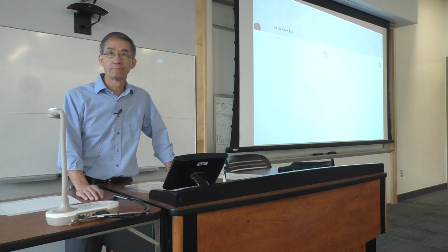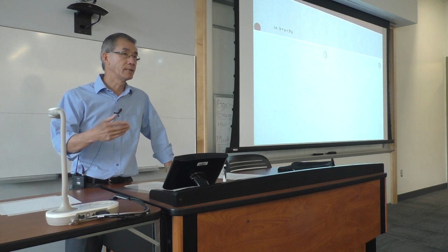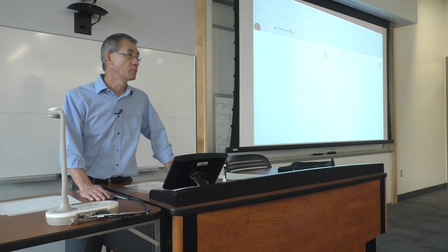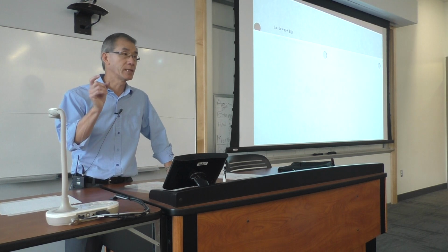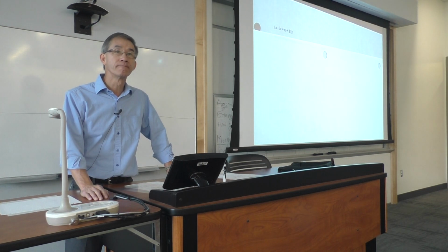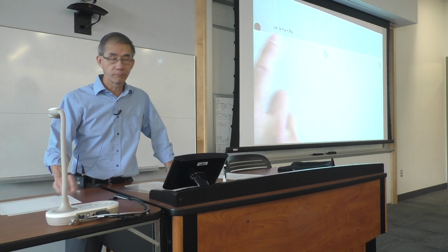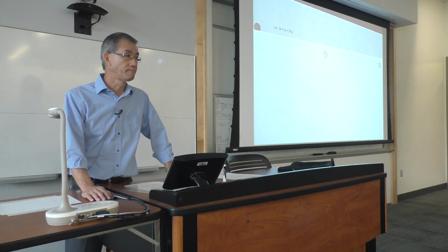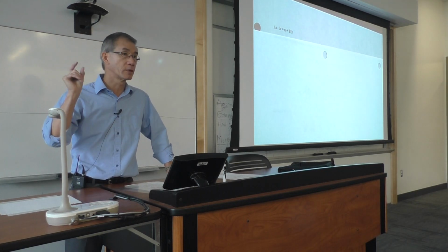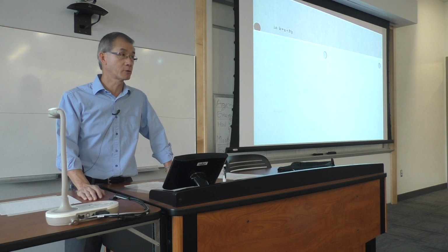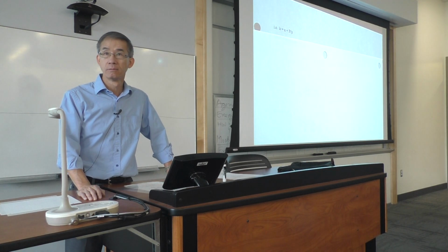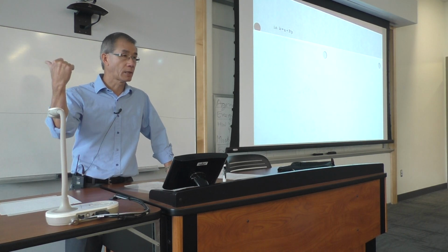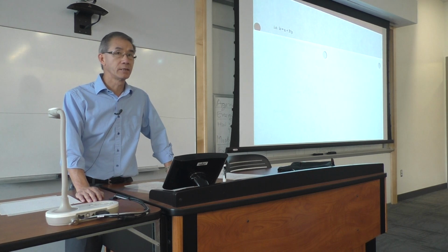So here's why. The motion of the fluid entering my device in the control volume resulted in some pressure or flow work, and it's represented by P times specific volume. And hence you replace the internal energy with enthalpy, H, not height. Do you appreciate that? Do you understand what I'm saying? Have you seen that in thermal? That when you go from your system first law to a control volume first law, you replace U by H? Did you ever ask why? No? Here's why. Question on that detail?